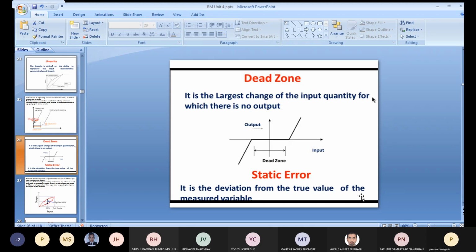It is the difference between the true, defined value and the measured value. Many times while handling the instrument, differences are created, because as per the standard conditions the instrument gives certain outcomes, but after a long time, long cycles, or lots of use, that deviation will occur. So that we call a static error.